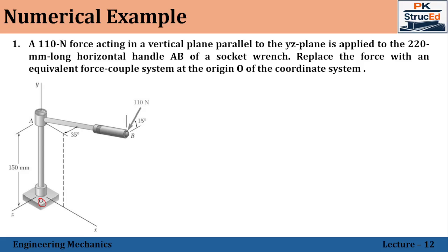The couple moment obtained in a wrench has a specific direction that indicates the axis of rotation, and this direction is determined using the vector cross product as well as the right hand rule. In design, the direction tells us whether the applied torque tightens, loosens, or causes any unwanted rotation.